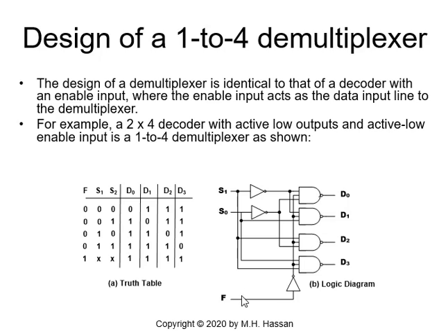And so by this, you can transmit the data accordingly, based on the select lines, to any data line. If you control F by a specific clock to transmit at a specific rate, you can transmit the data accordingly. S1 and S2 can come from a counter, where this counter will transmit the data in sequence, and the data will be transferred to D0, D1. So the incoming data is synchronized by a counter, and you can put the data on the data lines.